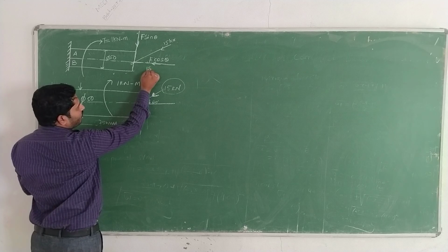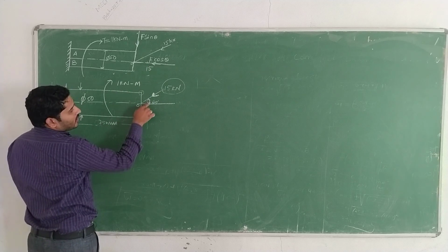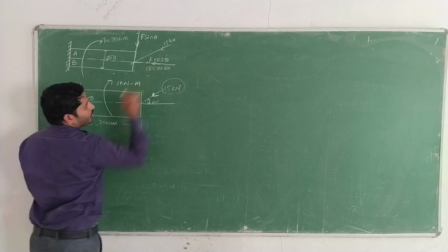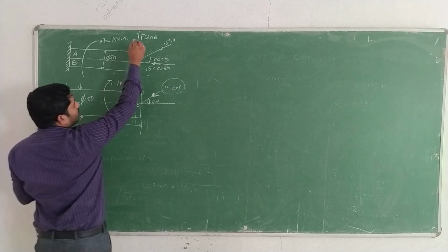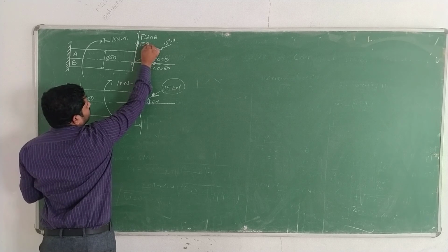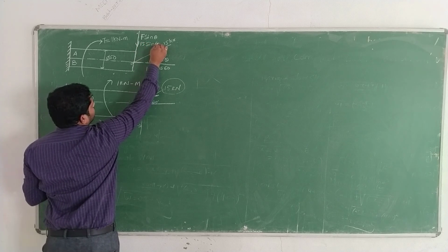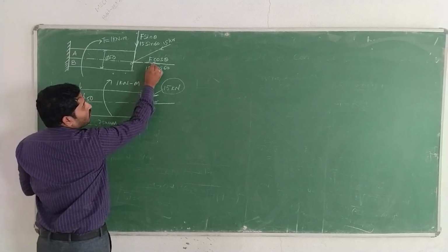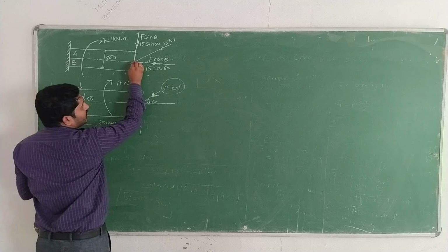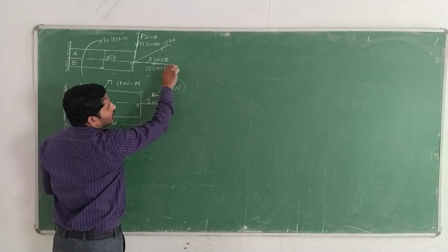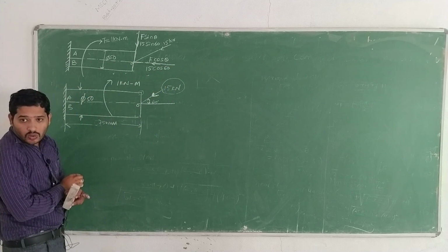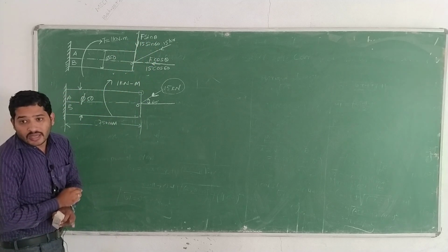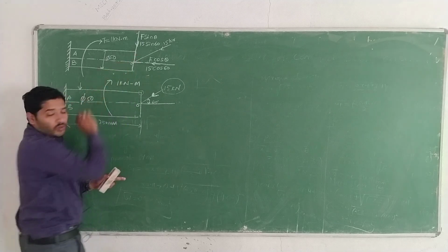Okay, dear. How much force is acting at the point O? The force acting is 15. How much angle are they making? 60 degrees. So cos 60. What about here? 15 sin 60. So 15 cos 60, which load is that? It is assumed as the axial load acting at the point O. And what about 15 sin 60? That is the bending load acting at the point O.